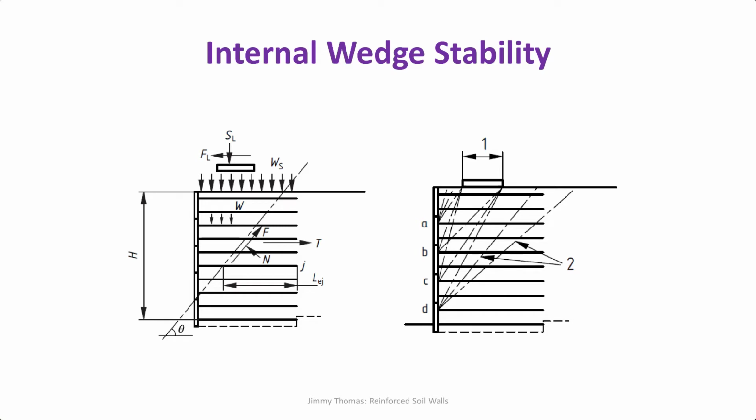Here each wedge is taken, then the total force in this wedge is compared with the available resistance; we add up all the contributions, then analyze the stability.